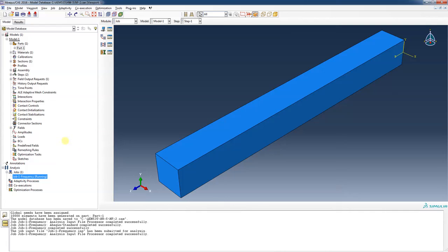Right, so this is running. We'll let this go for a little bit. I suspect we'll be a little bit closer. And so instead of changing your mesh density, you can change your element order, and you can try to find quicker convergence. There is a computational cost to using higher order elements.